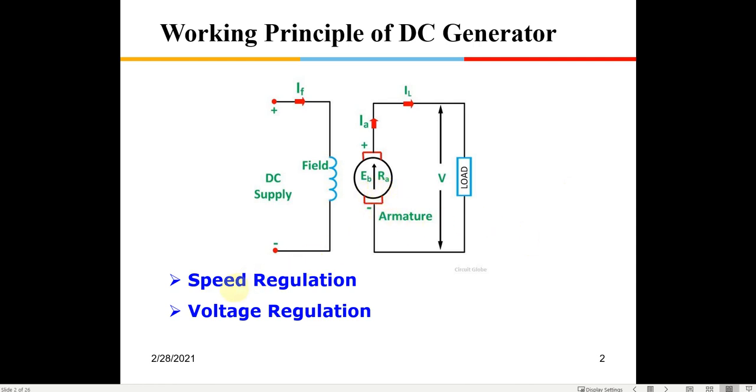That is how the speed regulation is done. That is where the law of conservation of energy holds good. More electrical energy being consumed increases the torque, and to maintain the speed you need to pump in more fuel. The diesel engine will burn more fuel, so that the law of conservation of energy is satisfied.